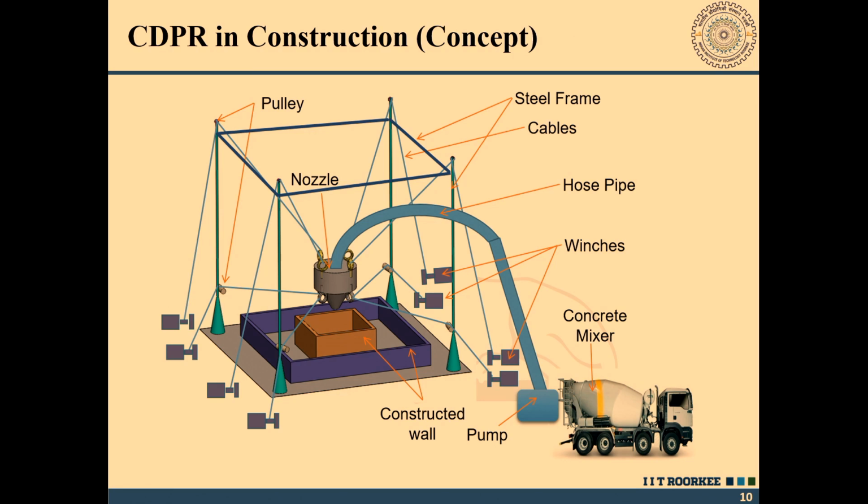Basically, they could be attached on the frame. The house design can be kept as, say, a solid model or whatever design you want, and then the trajectory for this design to follow could be generated, and concrete can be poured. The only limitation we felt was the time taken for curing, because one cannot deposit concrete to a greater height, otherwise it bulges.